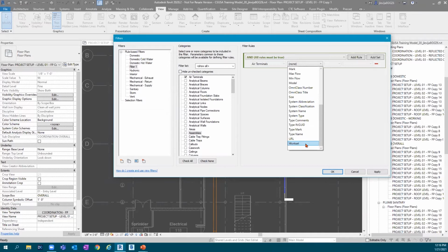Okay, so you get some flexibility out there, and this is where, when you dive in further with view templates and with worksets and everything along those lines, there are whole ways in which to manipulate and adjust your views, especially when you start adding in things like point clouds and you're linking in maybe an NWC file versus having that extra Revit file and stuff like that. So you get that flexibility out here.